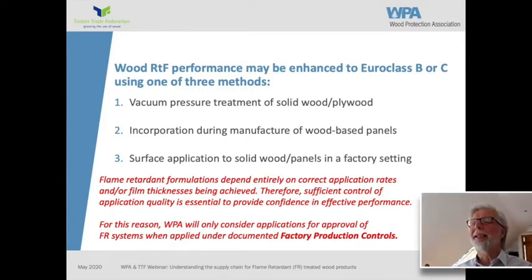If you test the product at a particular loading, then when you apply it for a project, it has to be applied at that loading to get the performance rate. And it's very difficult to ensure that is done properly on site. And so WPA, when we consider our approval scheme, which I'll mention later, on products, we'll only consider coatings applied under factory production controls.